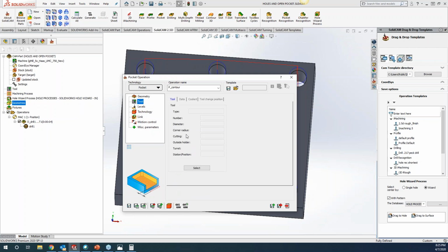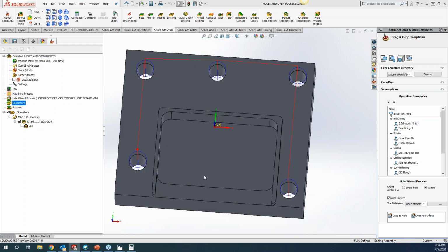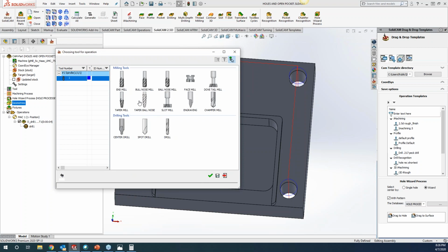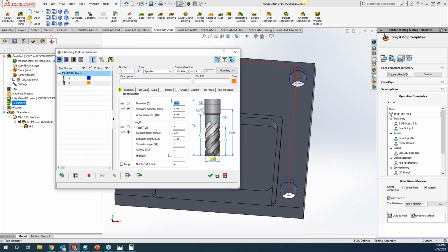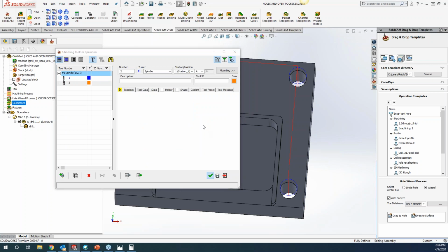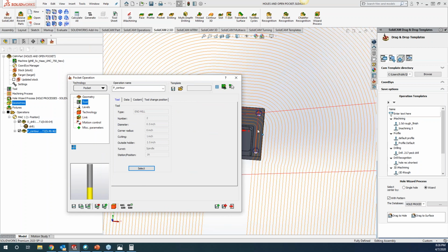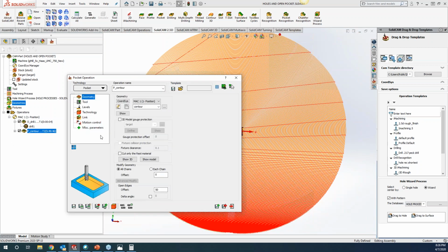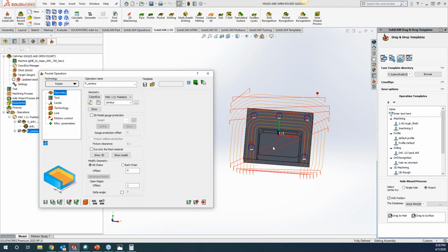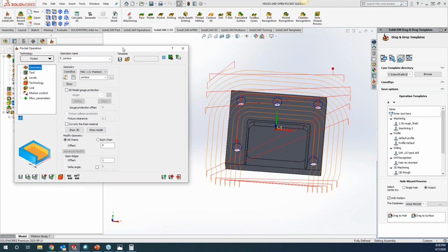Oh, I forgot to grab a tool here. We'll just go ahead and grab a 1/2 inch end mill. Okay, so right now, jeepers, there is a 50-inch offset in there. So let's go ahead and put that maybe at 1 inch, a little bit more realistic here. Yeah, you're really making sure that you're getting rid of that rest material. Yeah, exactly. Getting paid by the hour, right, guys? Okay, now, and we can go something even smaller.